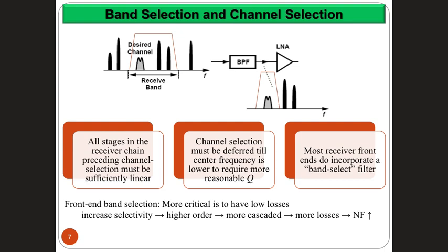If the previous component has very low gain, again lower than 1, then this means that the noise figure of the ones that comes after it becomes amplified, because we divide the noise figure by the gain. Remember that the noise figure at a certain stage, right, stage I, is divided by the collective gain of previous stages.